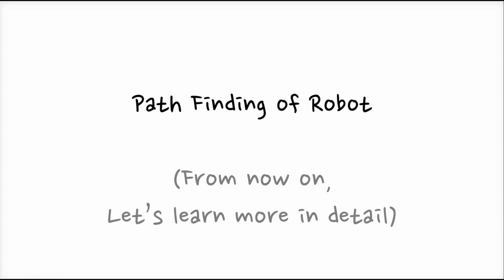And that's the thing that the robot does. If the robot has a rangefinder, and if the robot has an IMU sensor, or something that can help the calculation of odometry, the robot can draw the map.